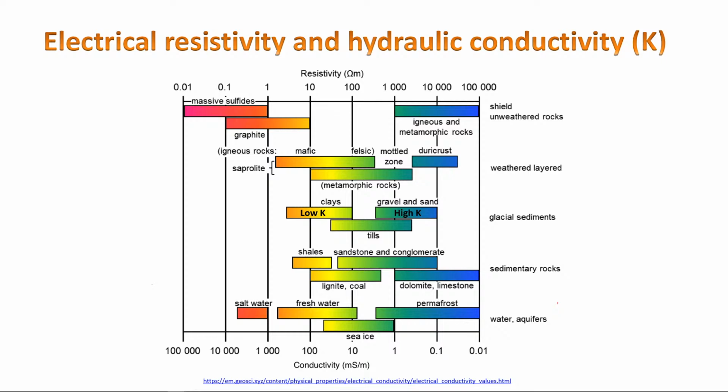You have your hydraulic structure and you want to know where the bedrock is, or identify features like sinkholes that could impact its integrity. Also potential seepage through sand and gravel units, or areas of clay, impervious layers that could also impact the integrity of your hydraulic structure.